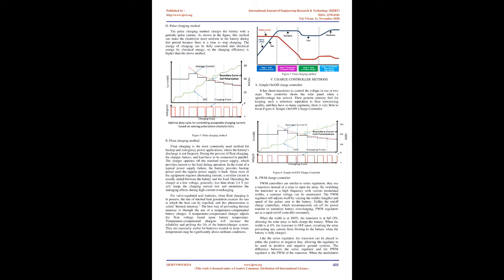B. Nickel metal hydride, NiMH. Nickel metal hydride, NiMH, batteries are the cadmium-free replacement for NiCd. They are less affected by the memory effect than NiCd and thus require less maintenance and conditioning. However, they have problems at very high or low room temperatures, and even though they use less hazardous materials, i.e., they do not contain heavy metals, they cannot be fully recycled.